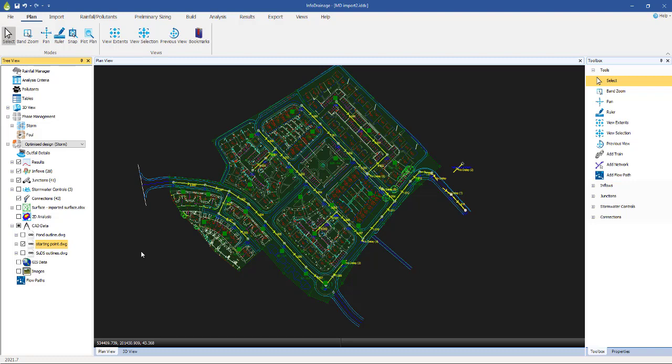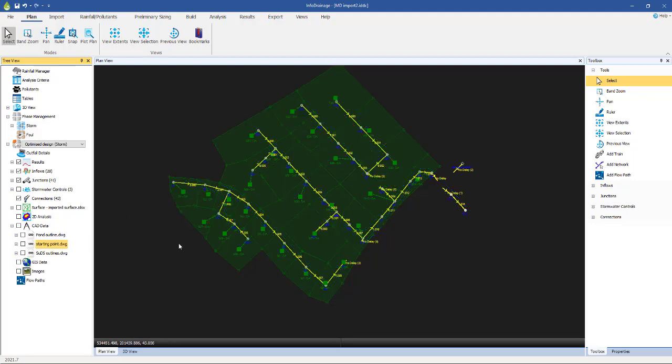But a crucial aspect of this is how much of the rainfall landing on this catchment actually makes it to the manhole. And as I say, that's dictated very much by the impermeable area which exists within each catchment. And that's going to be a crucial factor later on, which I'll talk about in more detail. So we've got our inflow areas. That's the third, if you like, building block.